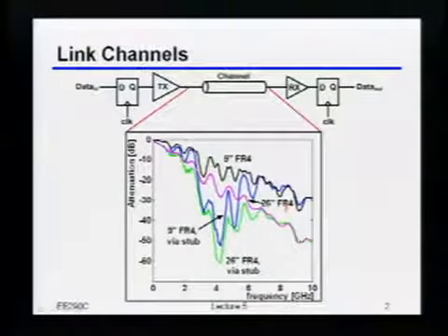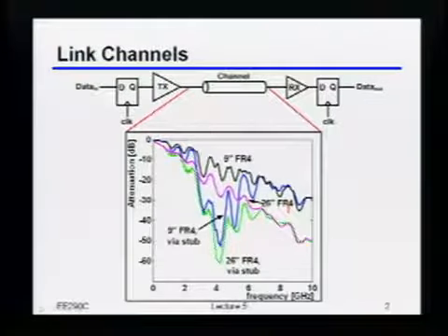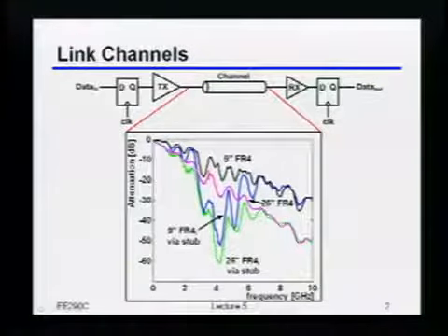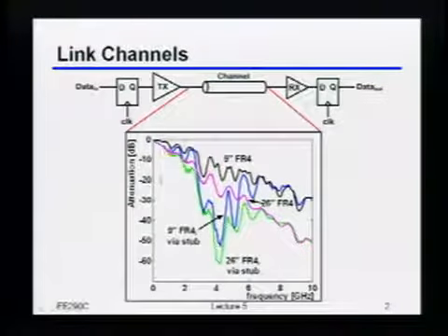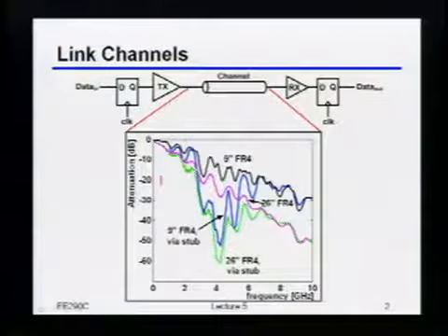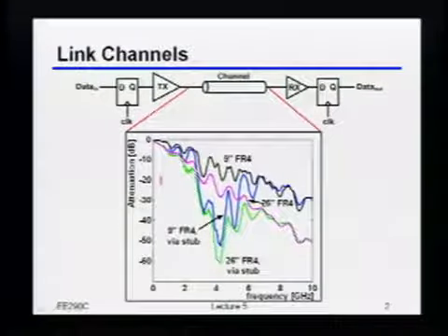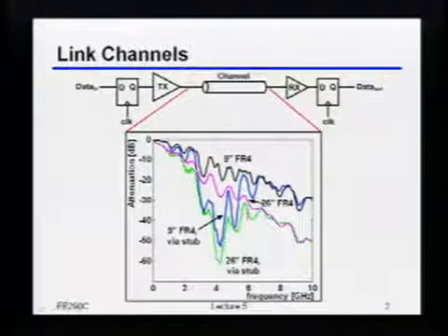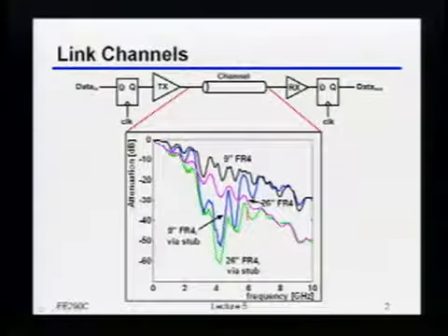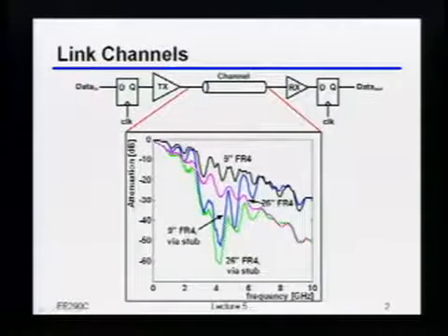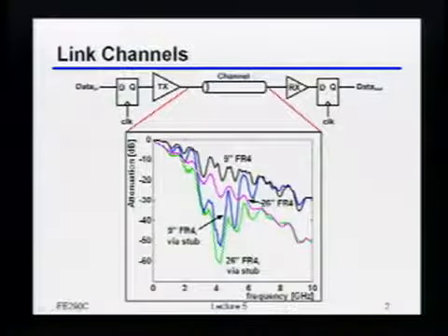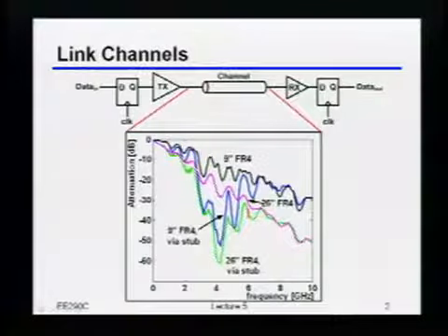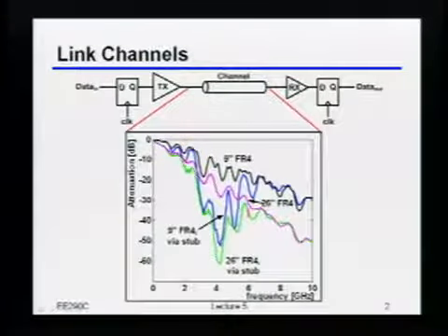Now, the point here is that if you take a glance at these, a couple of things should be immediately obvious. First, all of these are low pass, or band limited, so to speak. Meaning it doesn't look like you can go out to any arbitrary frequency because the loss starts picking up pretty quickly. The other, which we'll talk about more later, is that for some of the channels you see really deep notches and ripples. Those in particular are certain frequencies that just don't look good.